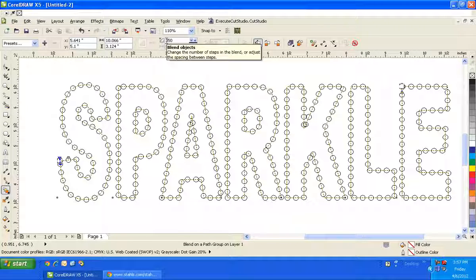But primarily, if you cut the circles too far apart or too close together, when you're going to brush those stones on top of those holes to fall into place, they're going to get caught on the lip of the circle that it cut itself. So it's going to be more production time. So you kind of just want a little bit less than the actual width of the circle itself.